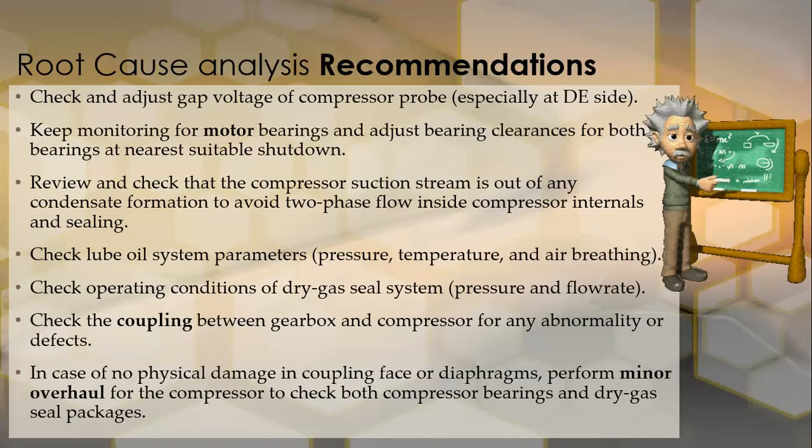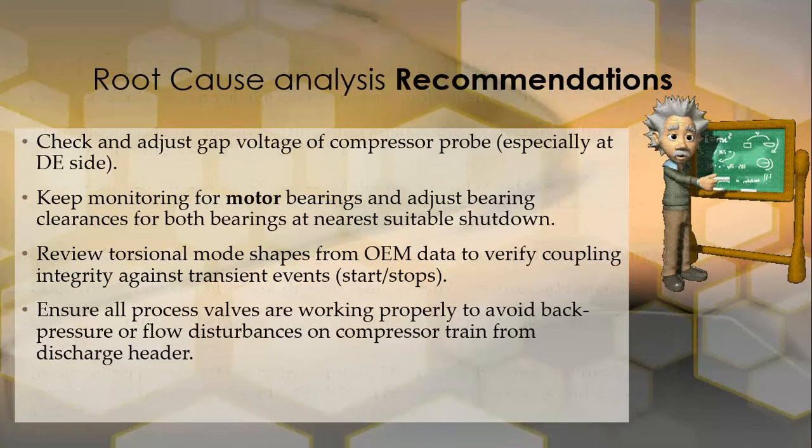We recommended also to check on the gap voltage of the compressor probe, especially at the drive end side, and to keep monitoring the motor bearings and adjust bearing clearances for both bearings at the nearest suitable shutdown. We recommended to review torsional mode shapes from the OEM data to verify coupling integrity against transient events.